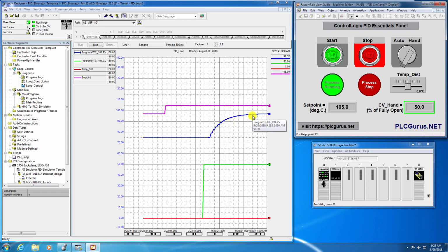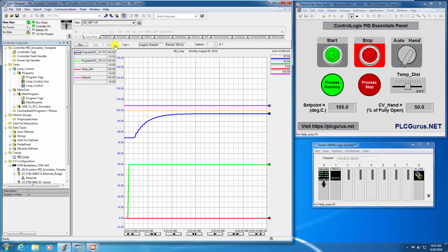And we did add a 5-second lag. So lag time is expressed in tau. So 5 tau is your total, or to get to 99.9% of your final PV position. Okay, so 1 tau, which is what we set, would be 5 seconds. So the total would be 5 times 5, which is about 25 seconds. Okay, and if we stop that trend and measure it now, we'll actually see that.